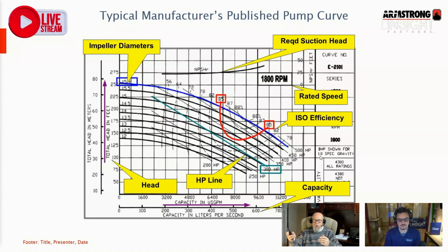However, I've been working on a job with a large customer running 15 to 20 degree propylene glycol in the system. That makes a huge difference on specific gravity and density. So it changed what we had to do from a pumping standpoint. It bumped our horsepowers up a little bit.